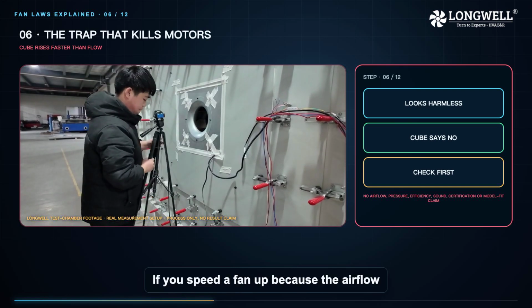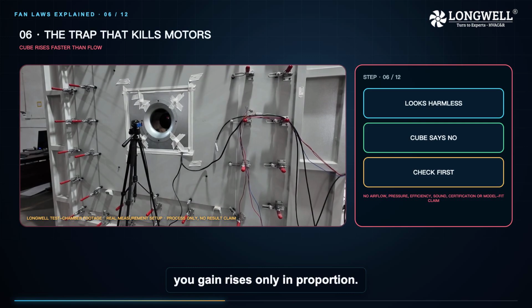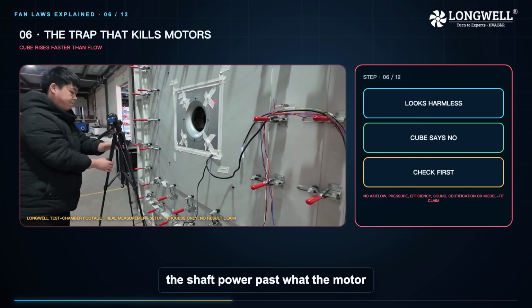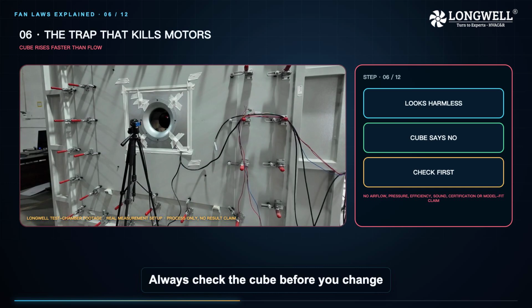Now the trap, and it is the reason motors fail. If you speed a fan up because the airflow is disappointing, the power demand rises with the cube while the airflow you gain rises only in proportion. A modest speed increase that looks harmless on the airflow chart can push the shaft power past what the motor was sized for. Always check the cube before you change a pulley or raise a set point.